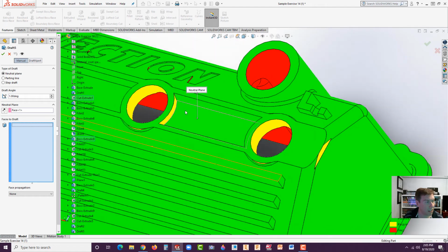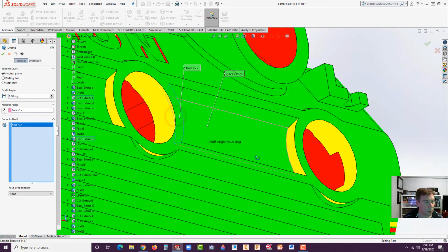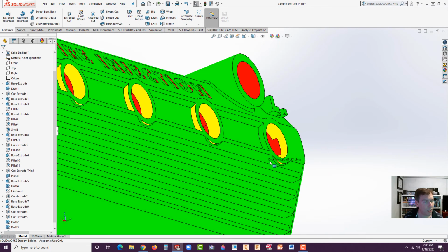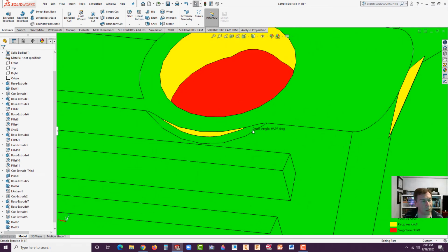Let's see if we could just get at least these in. So select that one and this one. Let's see if it works. Okay, that works. So these ones with the fillet, just beware if you want to get those in. They are really small, and working in mold design, especially with plastics, if it's a very small little segment, sometimes it's like, oh, it'll be okay. That's just a very tiny little, if it's 10 thousandths of an inch, just leave it. But talk to your manager before you do that. Don't take my word on it every time.